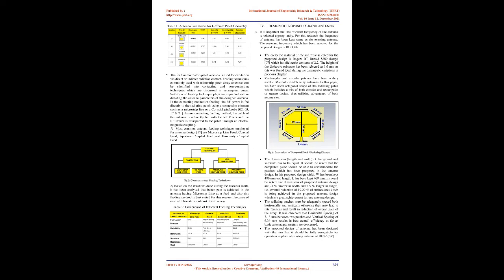Designing an antenna is trade-off engineering, which means that if we want one desirable characteristic, we have to compromise on another desirable characteristic. Keeping in mind the limitations and options available with the simulation application in hand and the scope of work, a number of parametric variations have been performed in the subsequent paragraphs. However, for parametric variations, the results of the single patch are considered and analyzed. Comparative analysis has been done side by side using at least 4 iterations for each idea, so as to obtain the best techniques and dimensions for the design of the proposed X-band antenna having efficiency improvements.